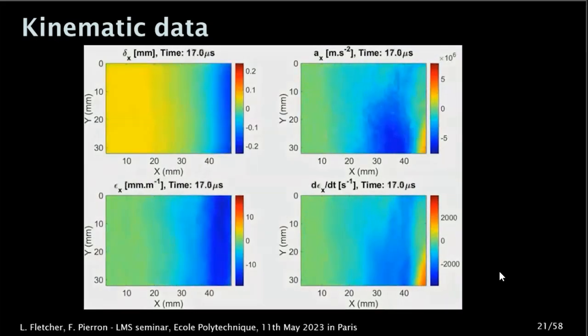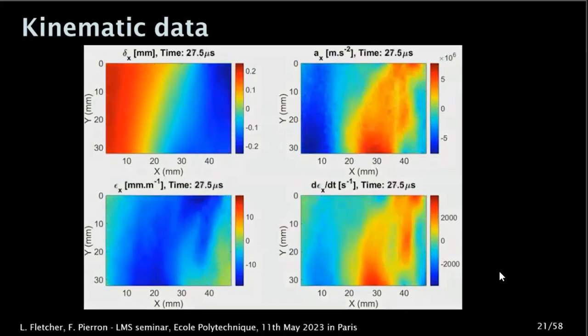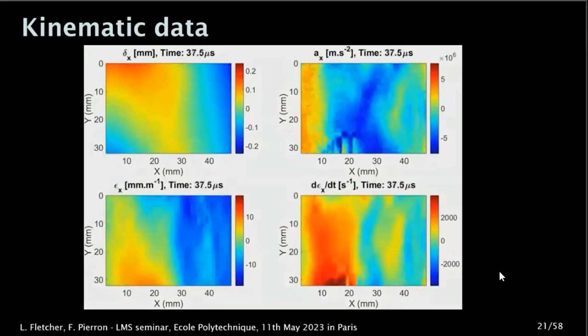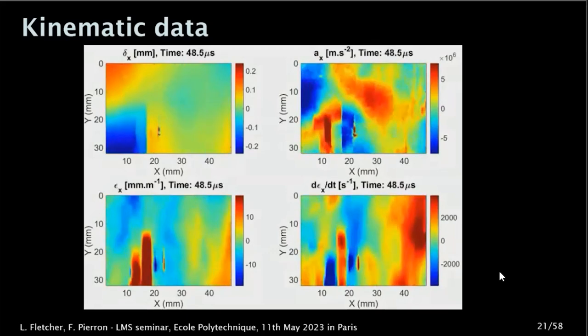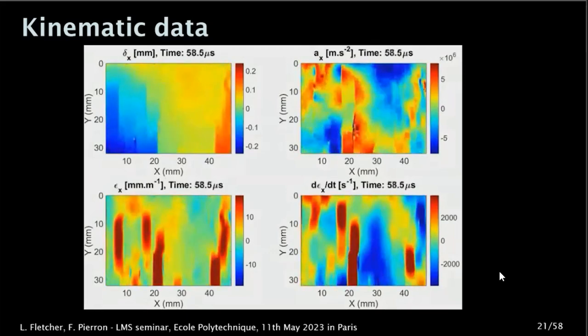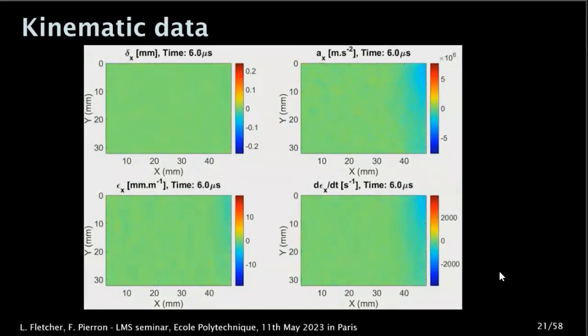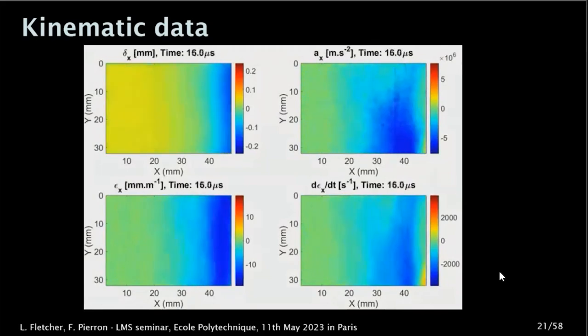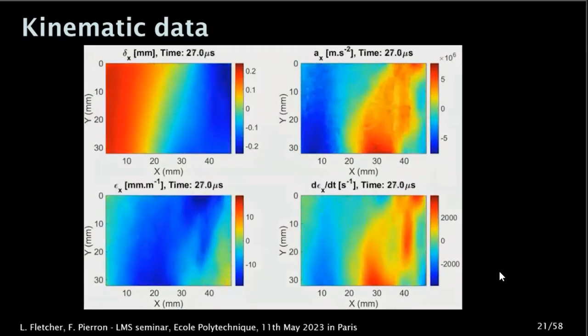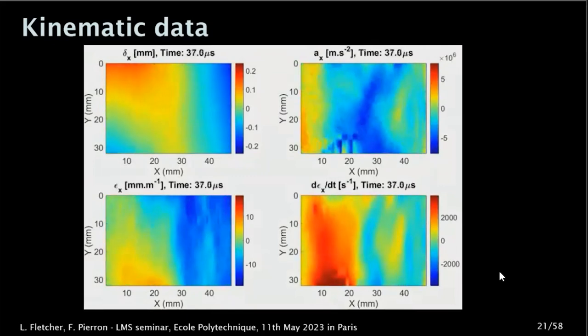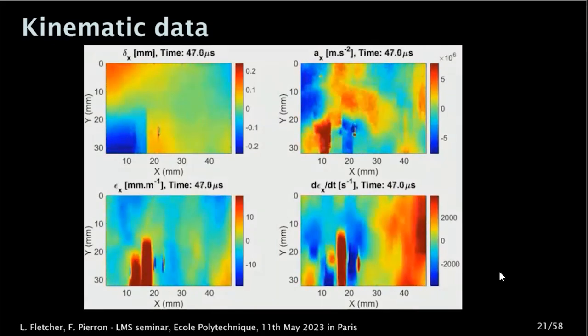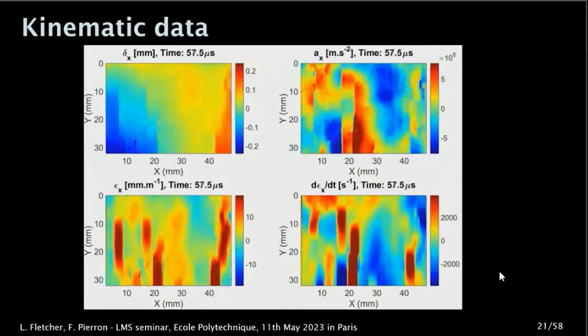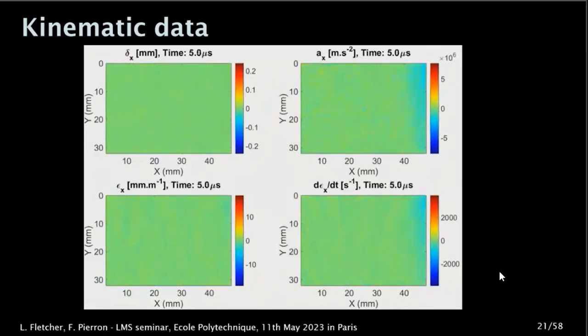And you see the wave coming from the right-hand side. This is the strain, compression strain. Then the wave reflects, goes into tension. And here, this is actually a crack opening. It's not a strain anymore. It's going to play again. You can see the crack better on the displacement map. The wave rebounds, and then you start to see discontinuities here. These are cracks in the 90-degree direction starting to form.